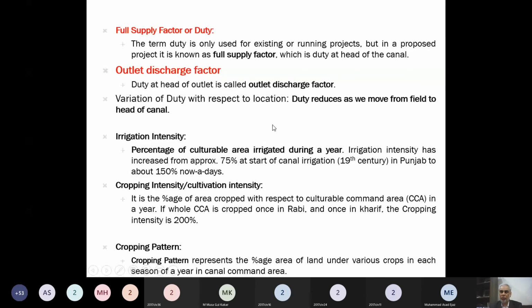We have to give you some terminology. We have given you some concepts of how much water can be stored in different phases of moisture content: hygroscopic moisture, field capacity moisture, and from there we have given you the concept of available moisture. Then we have told you that out of the total available moisture, try to irrigate when 80 or 70% of that moisture is depleted. Don't wait for 100%, because in this irrigation system, we don't have surety that we will be having water when 100% is depleted. So try to keep some factor of safety and apply water before reaching the wilting point or the lowest value. So you have been given the concept of water scheduling using demand-based irrigation.